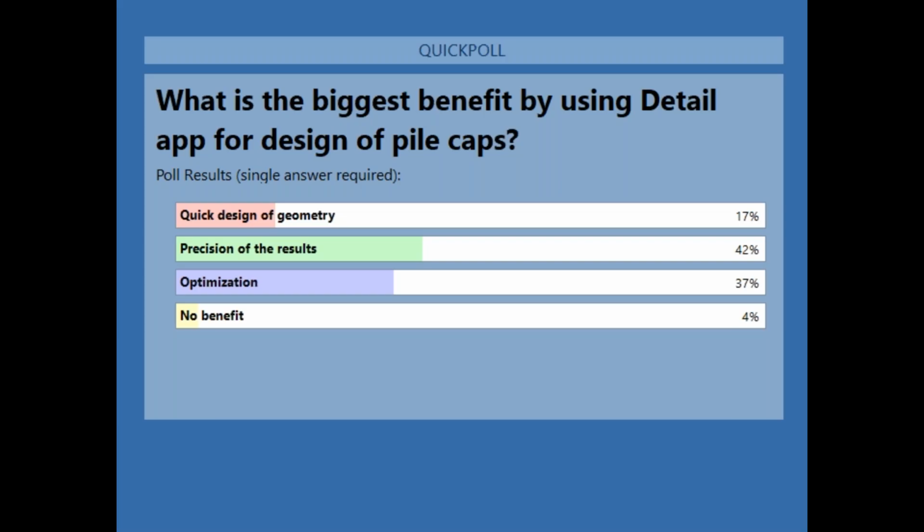There is the option to create the pile caps with the circular section, but it's very complicated. Generally, just keep in mind that there are some assumptions of the plane stress task. So it means it's only in the plane. Generally, the modeling of the circular sections is not so supported. You need to create some workaround there, but there is the option.